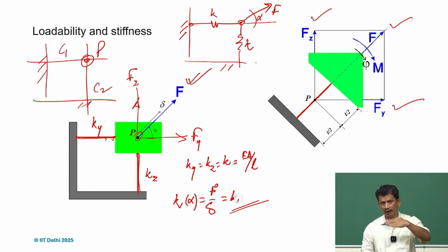If it's just one, under a pure bending moment, then P will be halfway. If we put two identical ones, or in general any two constraints or flexures, the point of intersection will give you the instantaneous center of rotation. So it's not lying in between the flexures, but away.